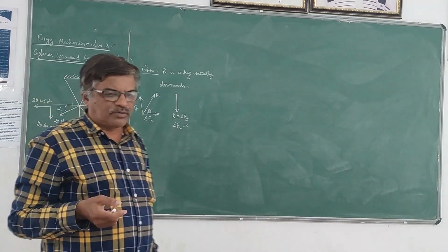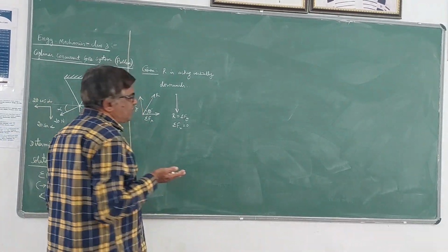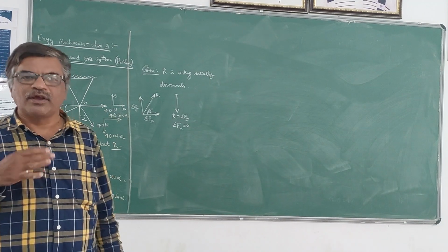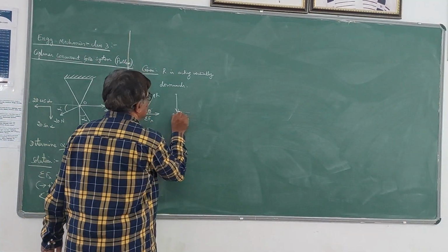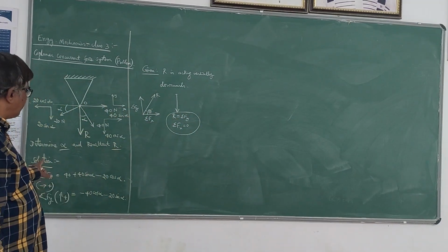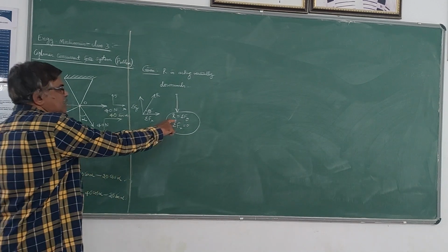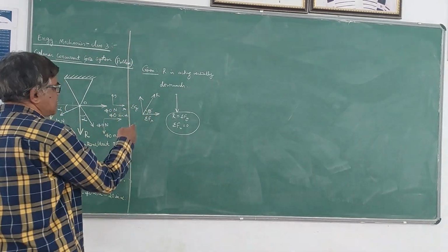Suppose in any problem they give that the resultant force is acting along x direction, then we have to take R equal to sigma Fx and sigma Fy will be 0. Now these two are the conditions which we have to follow to solve for alpha and R. We will have two equations, and we have to solve those two equations. Now let me apply the first equation.